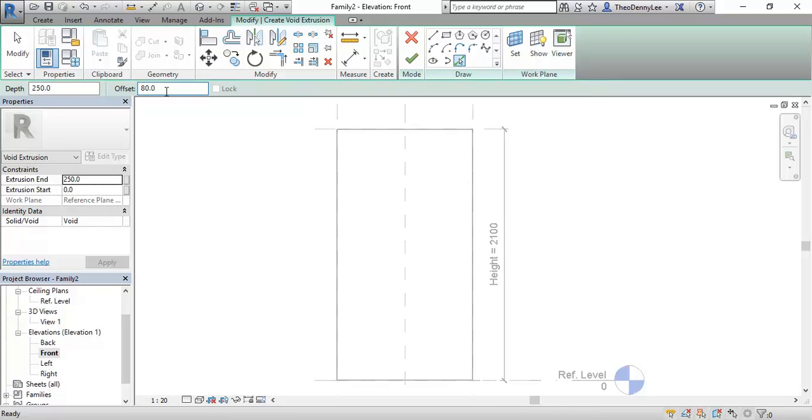Okay, I couldn't see that. Out of my vision. Okay, and then we go Tab. So when you move the cursor over the edge, you should see it'll offset one way or the other. So you've got to get it on the right side, and then usually press Tab after that.